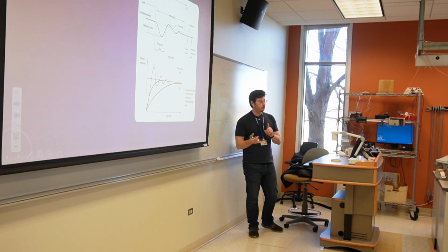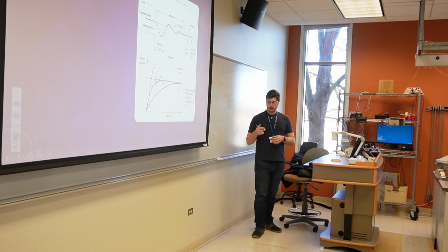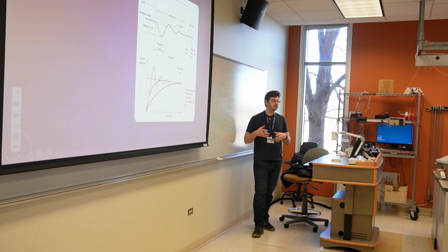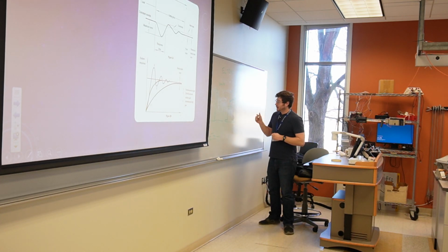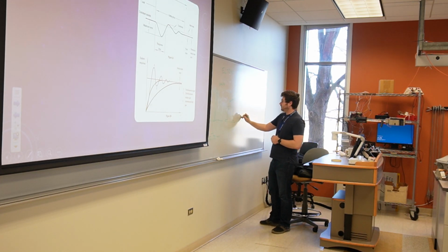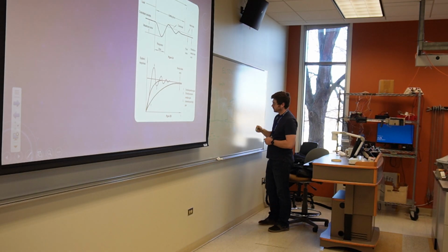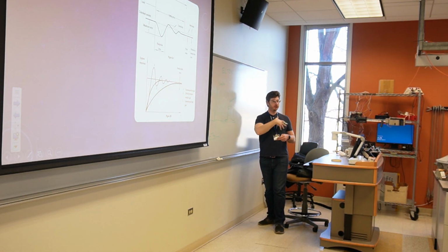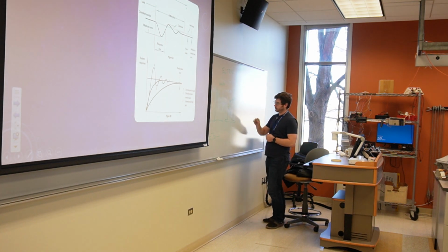I had to replace the electronics inside of it. So I needed to put a temperature controller in there because we needed to keep the cells at a certain temperature. And they had a nearby tank of carbon dioxide. A certain concentration of carbon dioxide inside of that system had to be maintained at all times. But it was really tricky to get that carbon dioxide to be the right amount, because if I pulsed the system, if I let in a lot of CO2 for just a second and then turned it off, the sensor that I was using had a really long response time, all right?